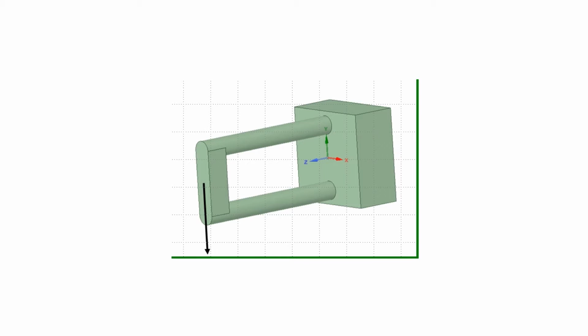the structure. Ansys can also determine the correlation between specified inputs, such as geometric and material property values, and specific outputs, such as stress and deflection. In this tutorial, we're going to look at the radii of two connected double cantilever beams as shown. We will look at the correlation between the radii and the equivalent stress. We will then optimize the size of these two beams based on a specific equivalent stress and the minimization of